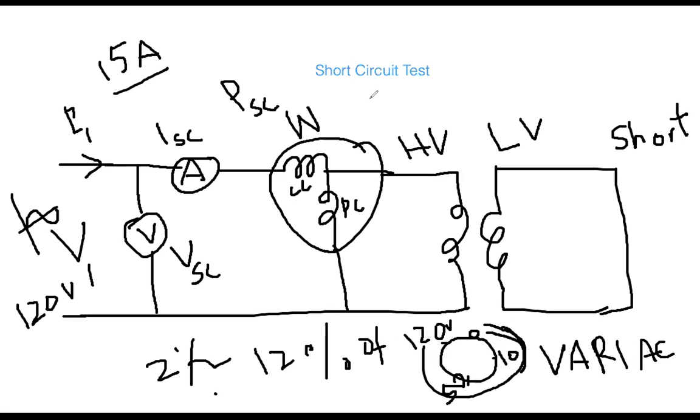So that's why, for the short circuit test, after making the circuit, the first thing is that you concentrate on this ammeter and very slowly start increasing the variac. Apply a little voltage at a time and go until that maximum point. Don't exceed that point.